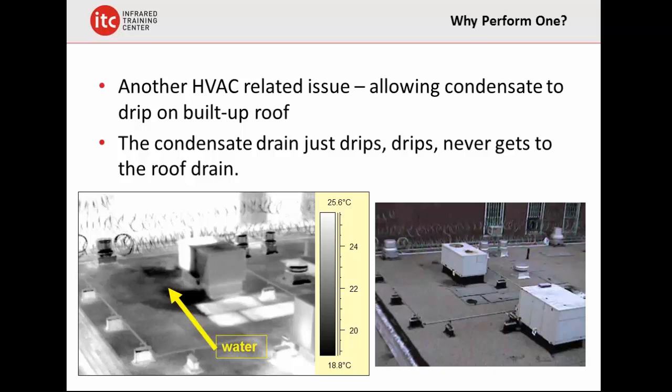As a matter of fact, the original roof that you saw, the EPDM roof from the Fleer building, prior to that, the tear-off roof, the roof that we tore off, was ballasted. It was EPDM in Massachusetts, and a lot of the images that we've used in marketing, and in previous courses, were from that roof. And a lot of the images where you see where we have ballast shoveled away and brushed away are from that roof. So yes, you can do it. I won't say it's easy. It's a little bit easier, but you have to be there at the right time. It's all a matter of timing.